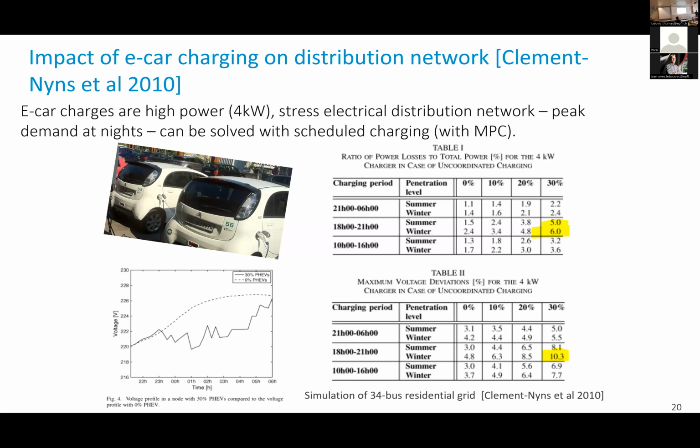If everybody starts charging their car with high power chargers, and depending on how the grid is done, if you're unlucky, then that will not work. It will not work, so there will be voltage or ampacity problems that will break some circuit somewhere. So you need somehow to control. So many electric car chargers are actuatable.